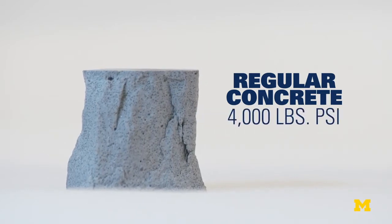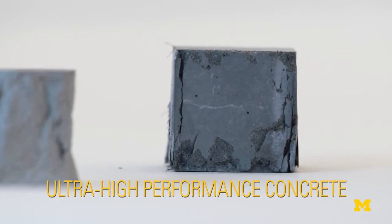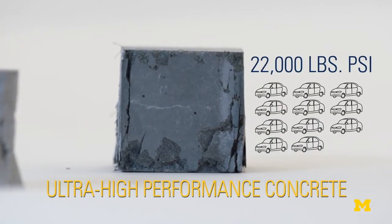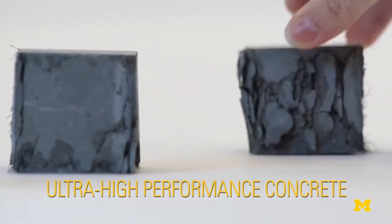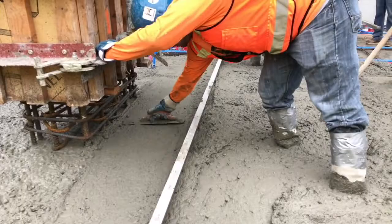After research, a high-strength composite concrete was found that included steel fibres throughout its design to increase strength and ductility. This was explored as a final material choice, although the increased strength meant that the cross-sectional area was to be too small and would jeopardise the column's reliability.